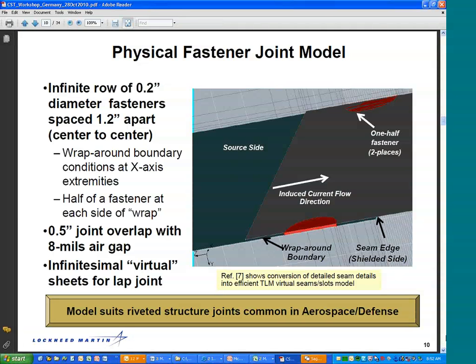The other thing is, with lightning, you have an added complexity, which was mentioned very effectively in the previous presentation: these fasteners are not only touching a homogeneous sheet of material, but there are non-homogeneous conductive fibers touching fasteners, and fasteners become a kind of bus bar for all these fibers, and it can be very complicated. But nonetheless, with these fasteners, the lightning energy, rather than burning through various layers and the resins to get to these fibers, can just do that at the next fastener that is tying the skin to the substructure.